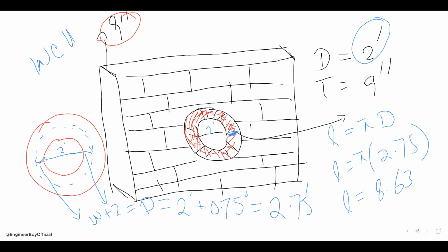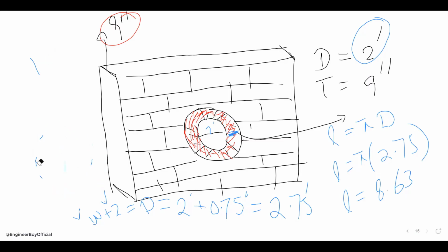Now we have the length, so we can determine the quantity of the same arch. Very simple. I'm gonna make some room for myself just by removing these things. Right now, the volume of the same arch should be the area times the length. Now, area, if you remember, the thickness of the wall is known, which is 9 inches, and that is 0.75.